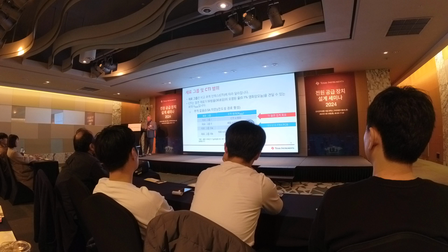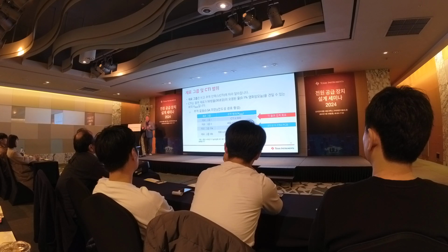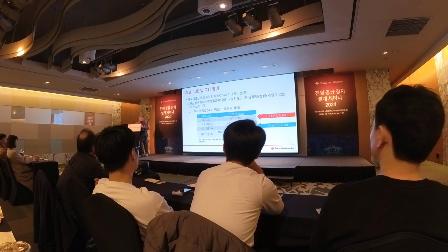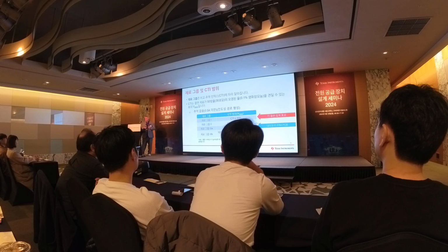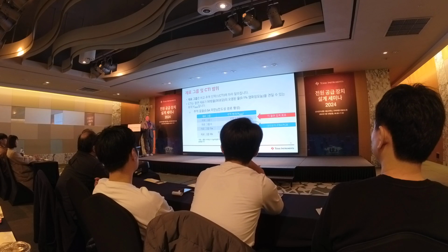And what you'll see as we go later into the presentation, because we're going to use components with different material groups in the same system, we need to take into account some other factors as well. And then the last one on our table is material group 3B. Material group 3B is between 100 and 175 volts, or if it's not specified, then we consider it to be material group 3B.